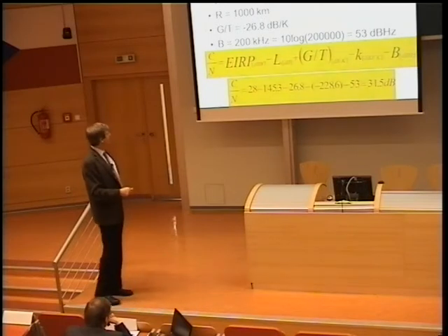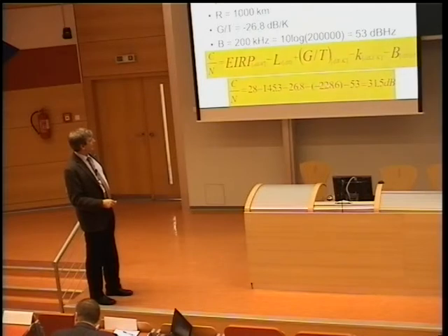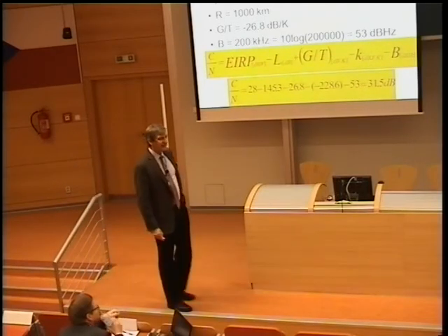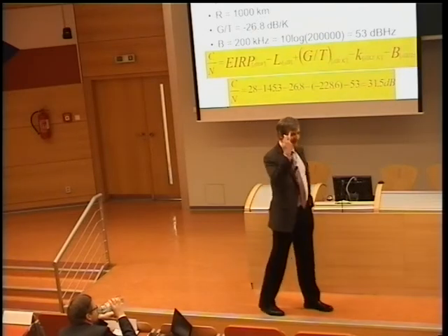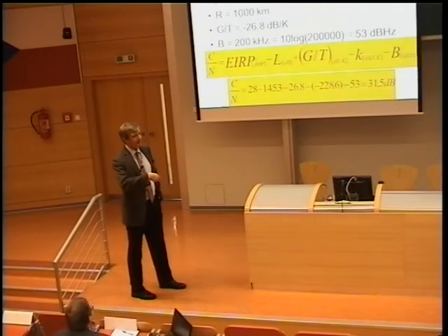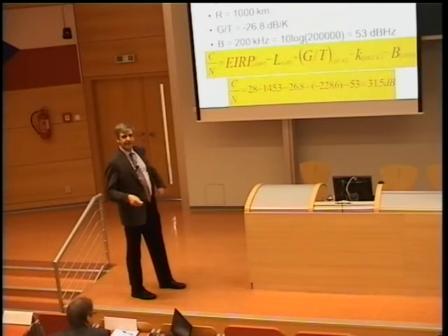And now, when we insert that in the formula, which you already know, here signal to noise ratio is 28 dBW minus free space loss plus figure of merit, but the figure of merit is negative. Then minus 228.6 dB joule per Kelvin, this is the Boltzmann constant, minus the bandwidth. So this ends up at a very healthy 31.5 dB signal to noise ratio. So this is plenty. So what it means, we could happily reduce the transmit power. We can play around with the Excel sheet later. So we could reduce the transmit power here, or we could increase the bandwidth happily.